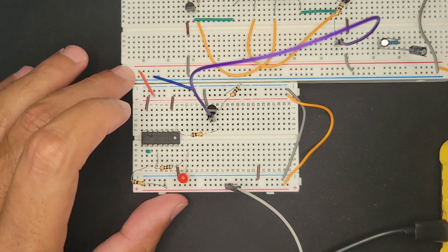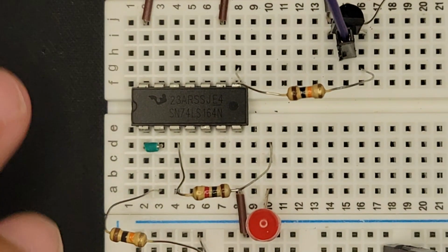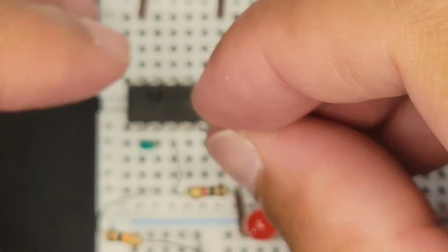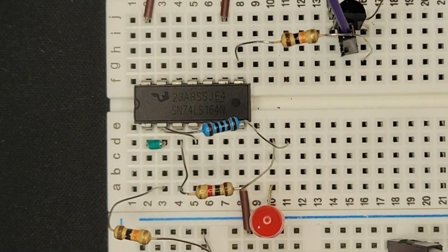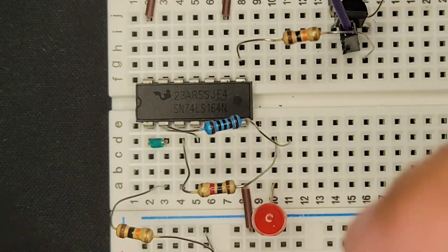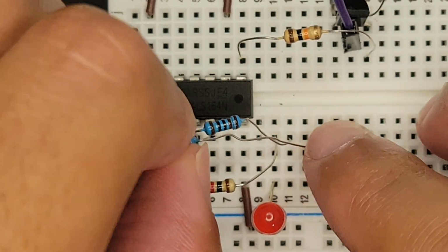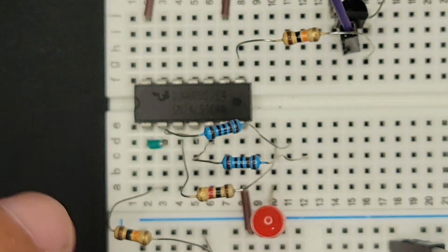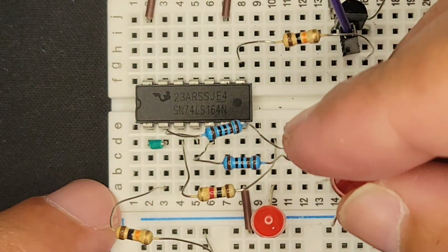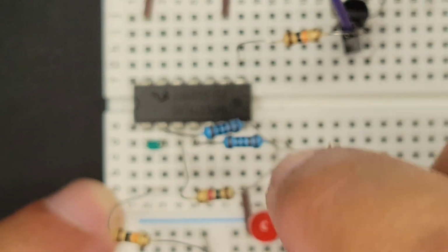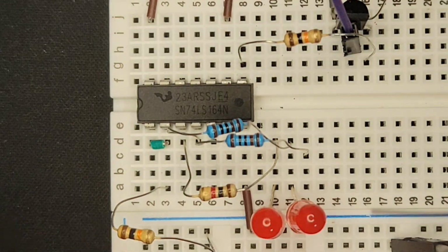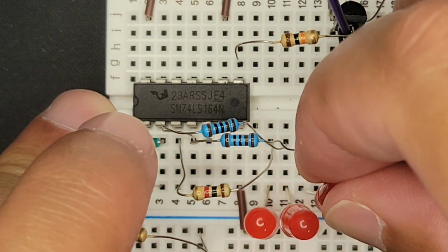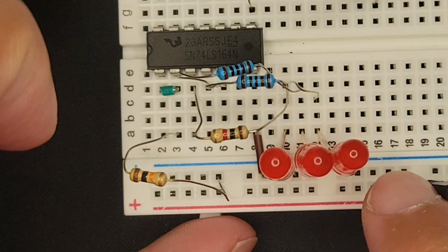So now what I'm going to do is take the output of B and C. I think this is a 1000 ohm resistor, so I'll just put them right next door. And then I should have another 1000 ohm resistor somewhere here. I think this is another one. And I'll put them right next door as well. And then we just need to put in some LEDs here. So here's one. It's for bit number 2, or output B, I think is what it's called in the setup. And number 3 will go right here. So we have A, B, C.